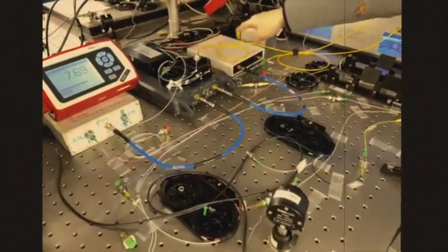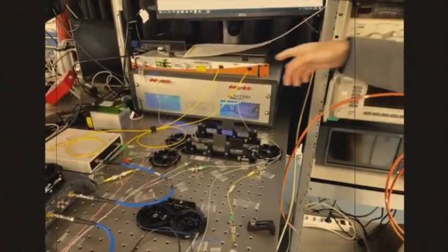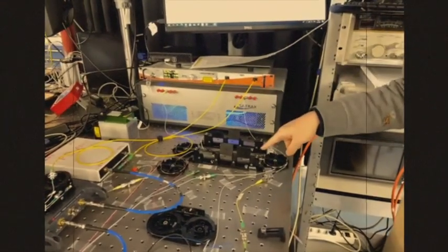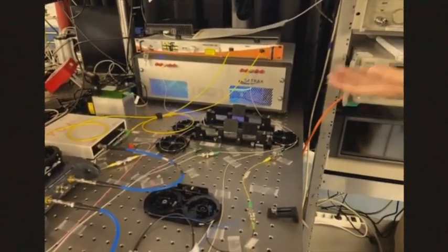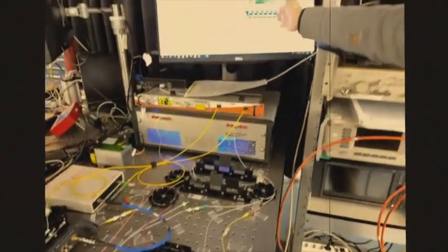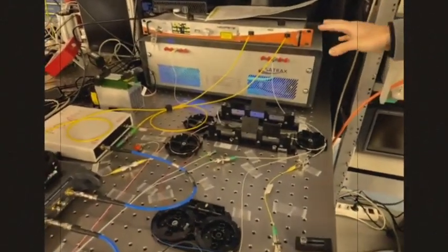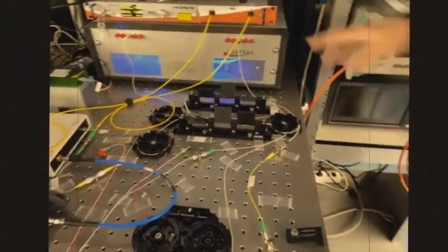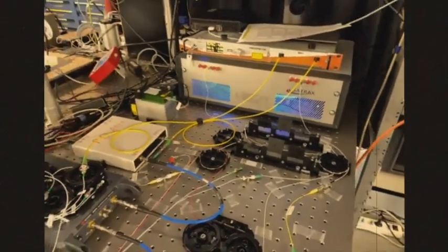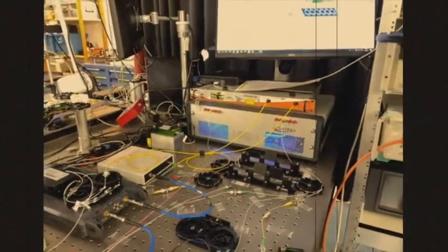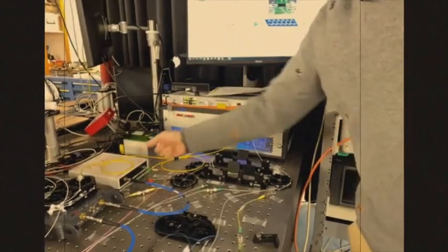And then the signal is sent into this optical amplifier. We increase the power level of the signal. After that, the signal goes into this polarization controller to control the polarization so that most of the light can transmit in the photonic chip with very low loss. This box, our photonic chip, it is actually in this box. And here we not only have the photonic chip, but we also have some heaters and the temperature controller to stabilize the response of the photonic chip. After this photonic chip, the signal goes to this photodetector, and then we can retrieve the RF signal back.